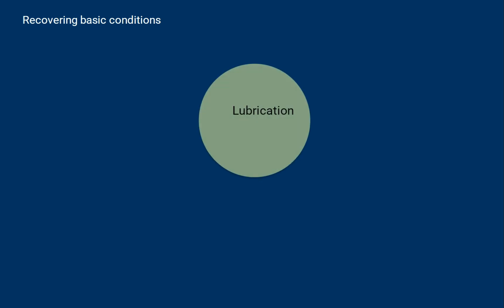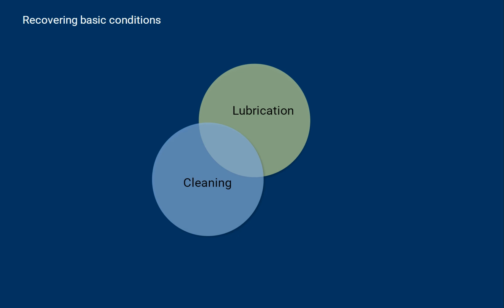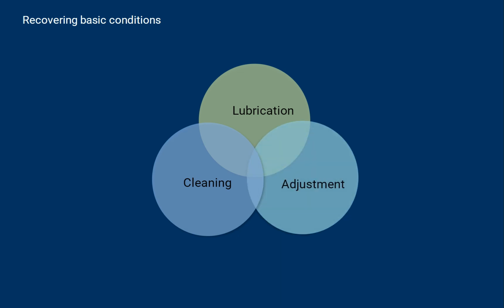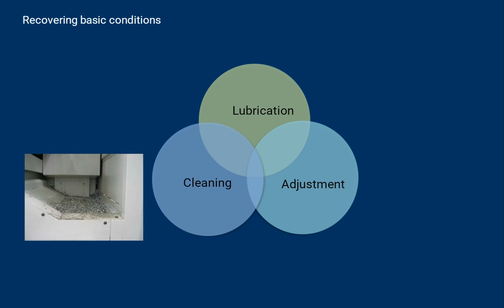The activities of cleaning, lubrication, and tightening or adjusting bolts are actions that determine the basic conditions of the equipment. To drastically reduce breakdowns and other issues in machinery, these basic conditions must be addressed systematically and persistently. Autonomous maintenance enables the maintenance of established conditions, improvement of equipment and work methods, and enhances people's awareness to aid in equipment maintenance. Cleaning involves removing any foreign substances or particles adhered to the equipment.